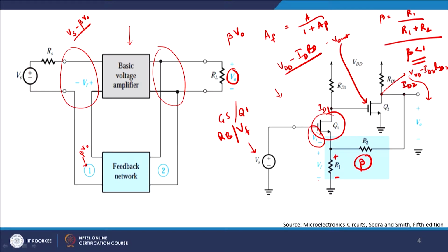The obvious reason why generally we have two transistors is that one is a driver transistor, and the other is a transistor which has been driven by this Q1, and that is the voltage which you see from the outside world, right, and you are able to sustain this formulation here. Depending on how you look into it, we will see automatically that by application of a reverse bias here, your input impedance actually rises with feedback.